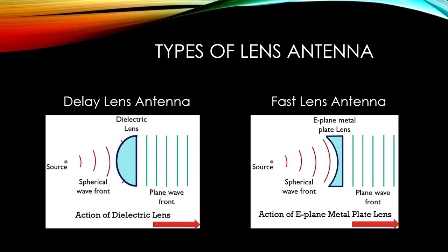Okay, so now the disadvantages. The low frequency use of lens antenna makes the antenna arrangement heavy and bulky. These antennas are more expensive than reflector antennas for the same gain and bandwidth. These are wideband antennas referred to as microwave antennas and are suitable for frequencies above 3 GHz. The electric lens antennas are frequency sensitive. Thus, this specific type is not used over a wide frequency range. So that's all for our lens antenna.